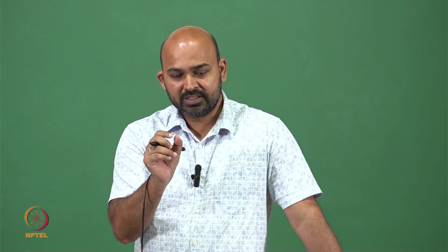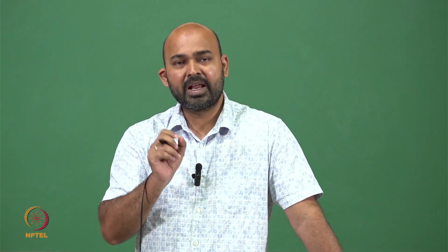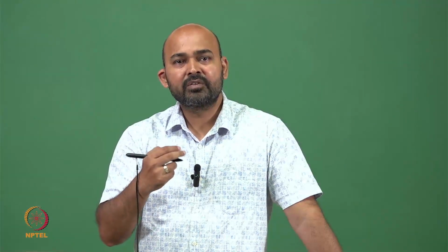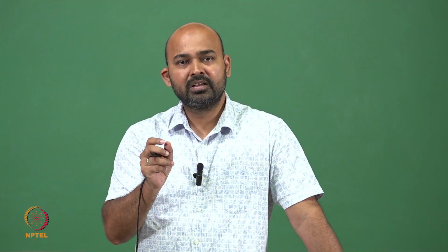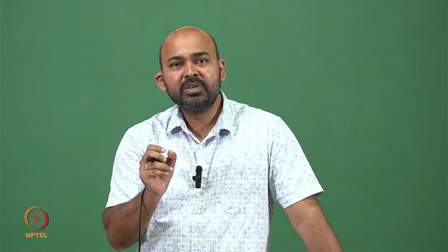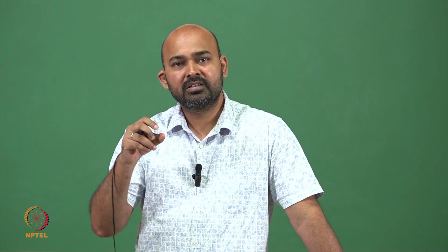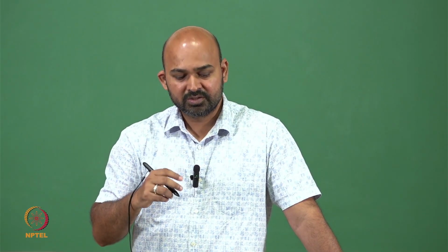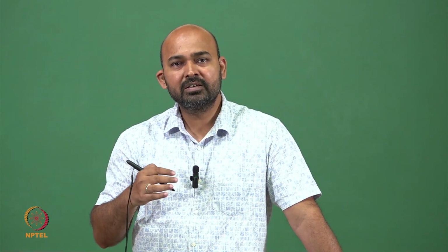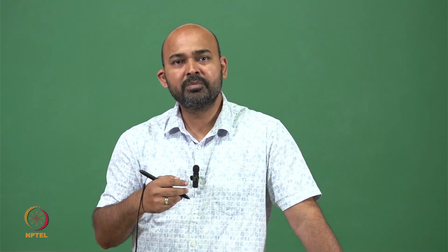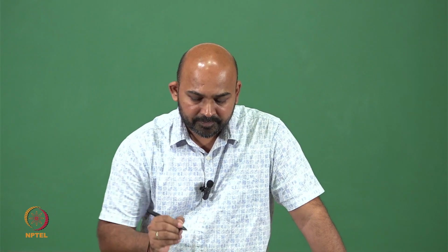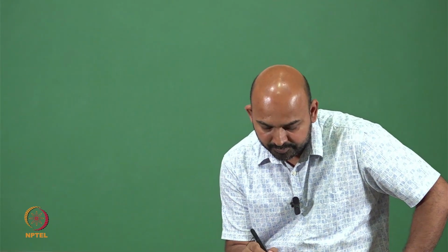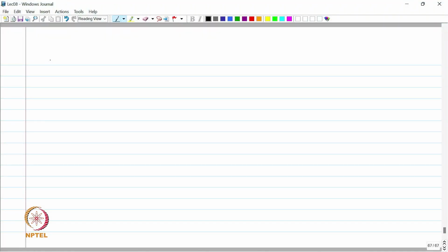Based on this spacing of the Bragg's grating, we can detect what wavelength is going to come back or going to be transmitted, and this spacing between the gratings is a function of temperature. So this is how you can make a temperature sensor using Bragg's grating based optical sensors. So we have Bragg's grating based fiber optic sensor.